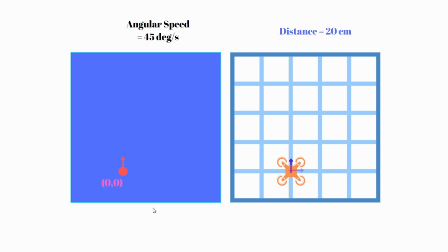So what can we do to actually find the coordinates when we are pressing both the forward button and the right or maybe the left button? We are rotating and we are also moving forward or moving backwards. How can we calculate that? By the way, the angular speed is calculated pretty much the same way as the distance. If you are moving for 2 seconds, 45 degrees per second for 2 seconds will give you an angle of 90 degrees. That will be your heading after 2 seconds.